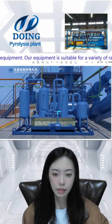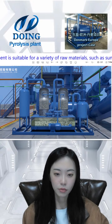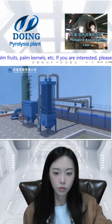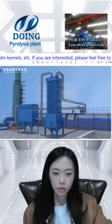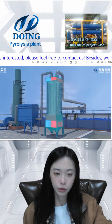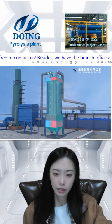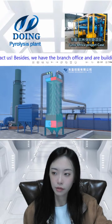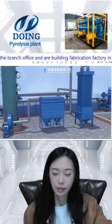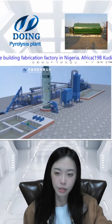And then this is our optional environmental protection device, the tail gas deodorization treatment system. The first one is the air-cooled cooling device, which can replace this water cooling. They have two choices. The second is a post-dust collector, which is used to remove the dust from the flue gas. And the third one is a glass fiber reinforced plastic desulfurization tower.